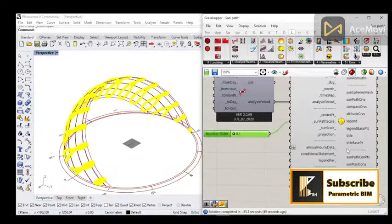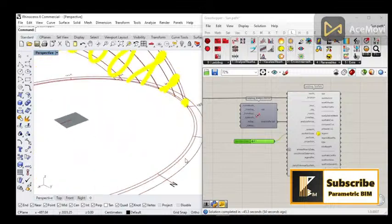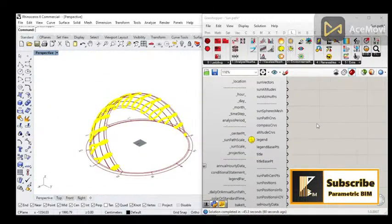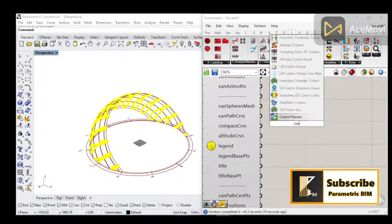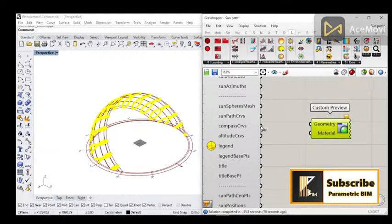Okay, another thing to show you: if you are not interested in the color of the compass or these curves of the sun, you can change them from the output here. For example, we have here sunpath curves and compass curve. I am going to use a custom preview component, and once I bring it, we can connect the sunpath and the compass curve, but make sure to press the shift key.